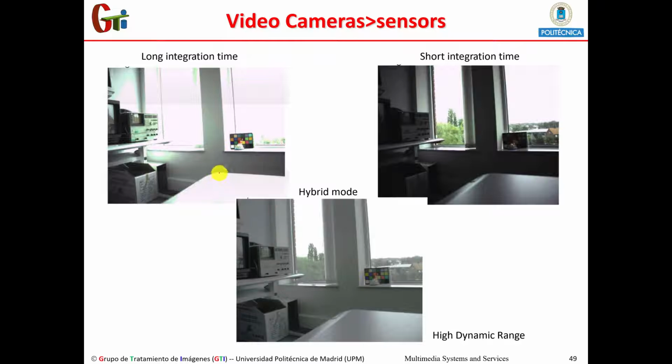That extension is useful because in the indoor image area, there is a low quantity of light and we need to collect light during more time to produce a correct image, so that the picture elements of the sensor are correctly excited. But those regions that have a great amount of light are just saturated, burned.